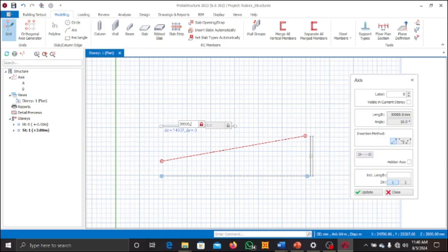You want to put it in the y direction. You can also put it, let's just say 1,000. Press enter, and you notice the grid has been created. On the x-axis is about the length, but then on the other, the y-axis is about the width. So that's how you create a single segment axis insertion, right?